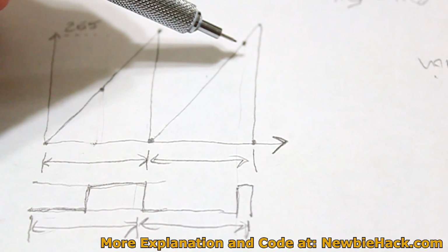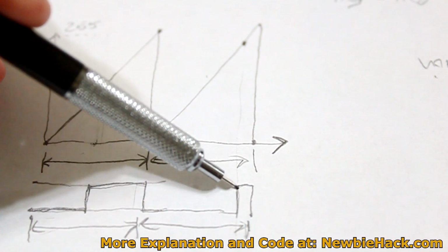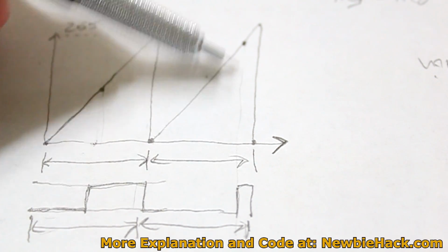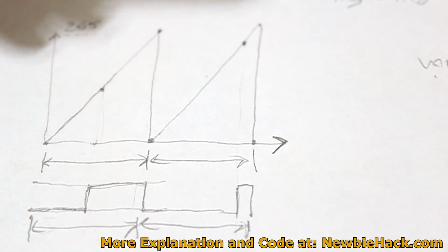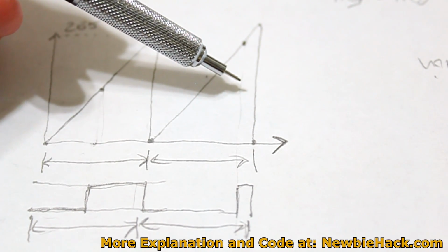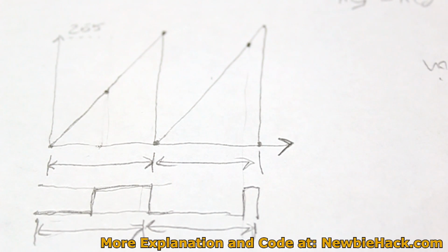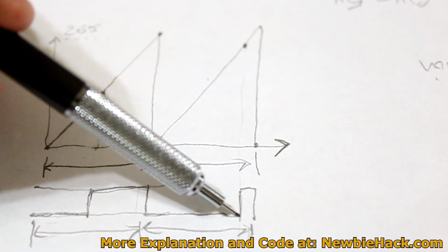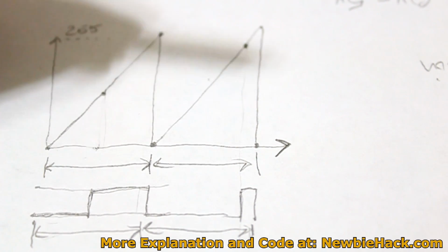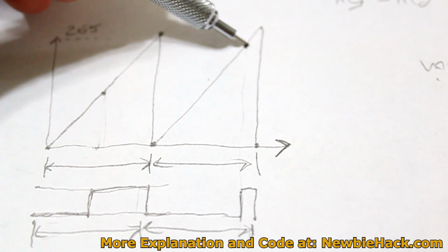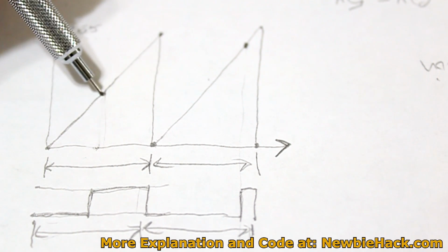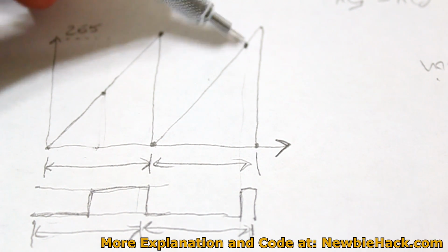We will look at this option in great detail when we're trying to control more than 4 servos. We can have as many servos as we want as we have outputs on the microcontroller. For the next tutorial with the servos, we'll be using the output compare pin, and we'll be using the internal function of PWM. So we're going to set a particular variable, or the output compare register, to this number that we want it to produce the PWM.